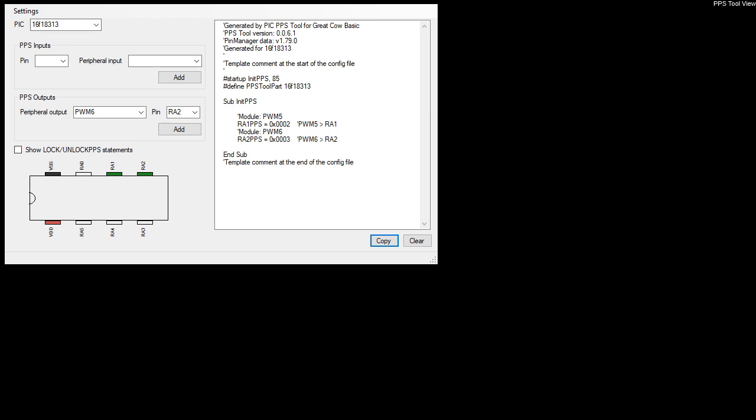Down here, I've got the same constants, but now these PWM numbers are different. I have to put 5 in here and 5. I'm going to change that to 6 and 6, and we've got the same outputs. But remember, this is a completely different module, okay? And because it's a different module, I have to tell it it's actually the pulse width modulation module. The other one assumed CCP, okay? Is that correct? Oh, it's gone blue, look. It's gone blue because it's valid, okay? There we go, great.